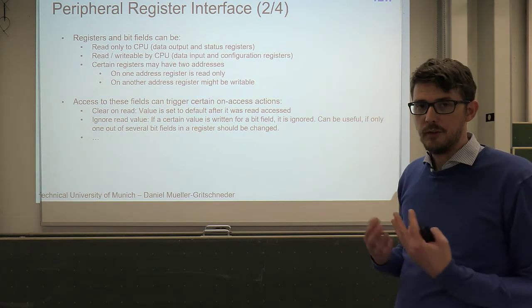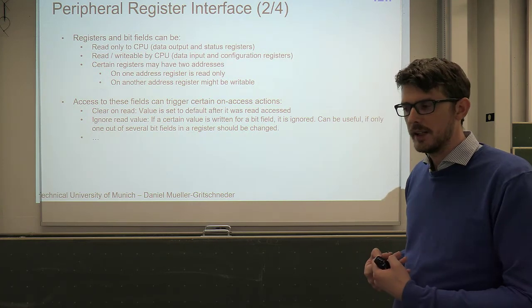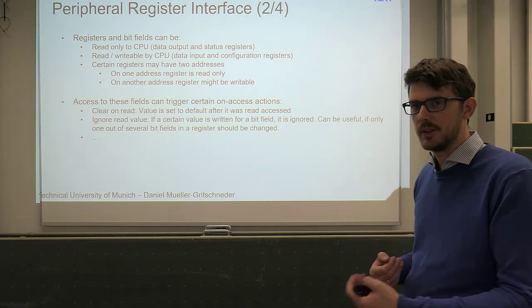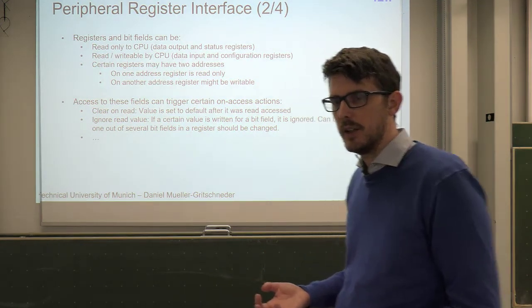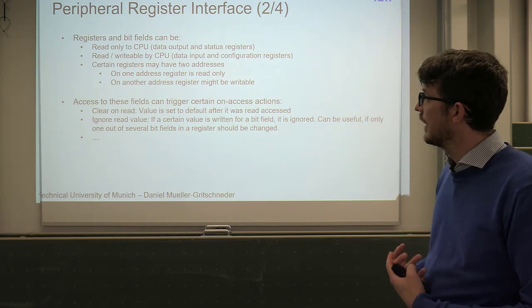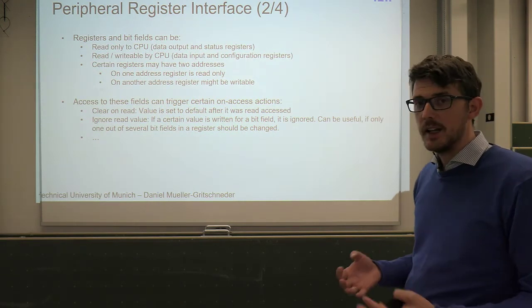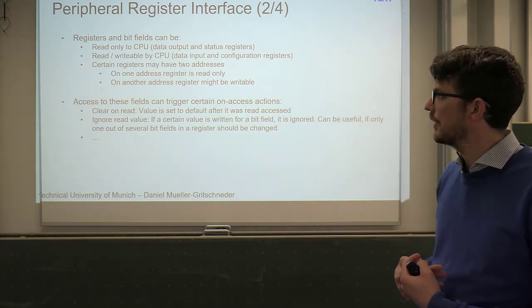And therefore, if this is a status, then the status is reported to you by the device, so you should never write to the status. This can be done by the device making this register read-only, so you're not even able to write to this one, right?